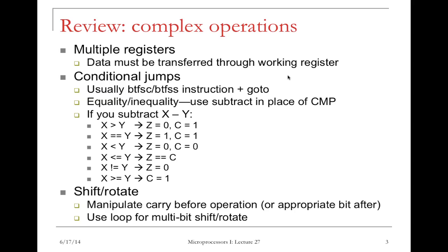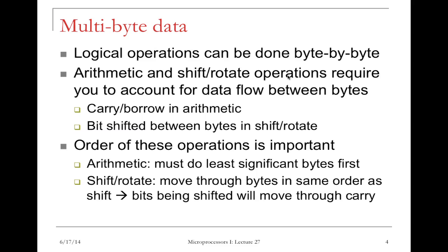For shift and rotate, you will manipulate the carry bit before the operation, and for multiple bit shift or rotation, you need to use loops to implement it. Logic operations can be done byte by byte, and arithmetic and rotate shift instructions require you to account for data flow between bytes.